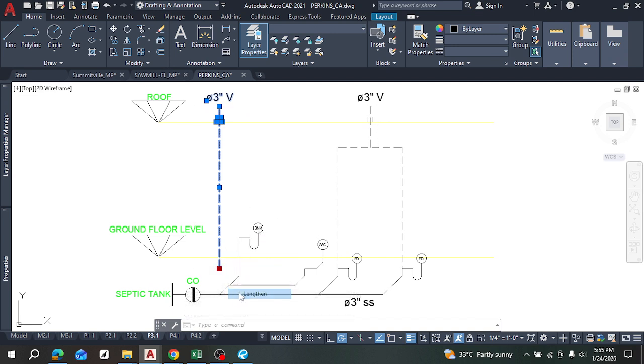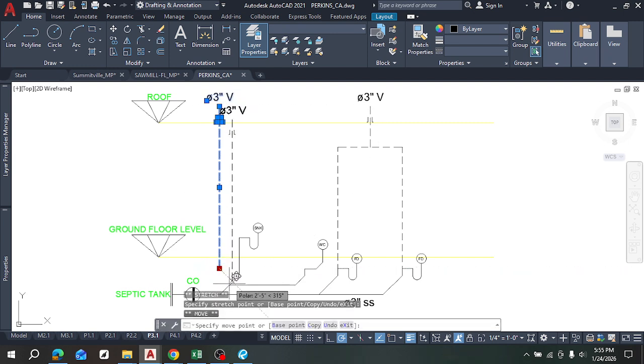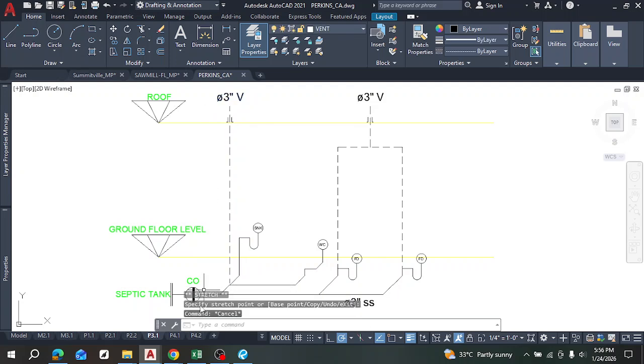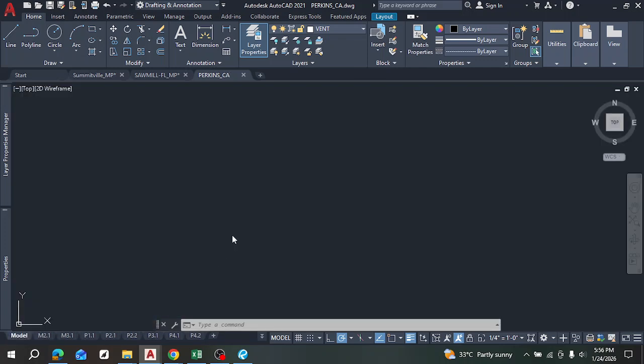So this now means I'm venting directly. Okay, I need it somewhere here. I'm venting around the point where it meets, right? So if I come here, okay, I'll extend this down here. Even though it doesn't make much difference, I like when it just meets what I want. Then if you see this one now, there are two vent lines that go off from the floor drain and then they meet up here, right? So let me save that and show you how that worked here.